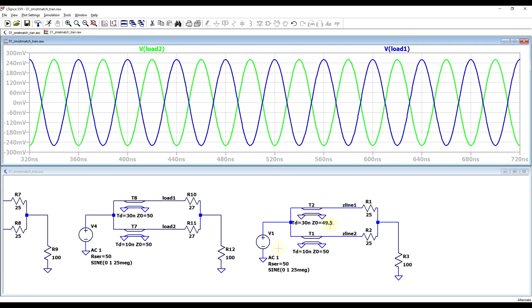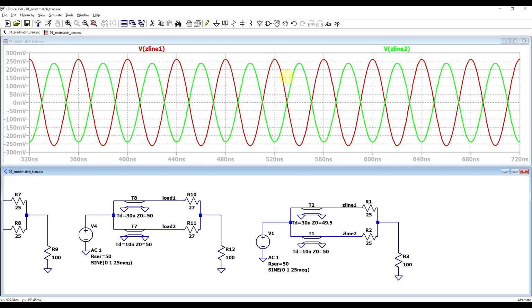So if we look at the response of this circuit, in which the cable impedance is different, well, we start to see a behavior similar to what we are getting. So at least in the simulation, when the line impedances of the two pieces are not exactly the same, we are getting a very clear imbalance in the two signals. So is this the problem that we're having?